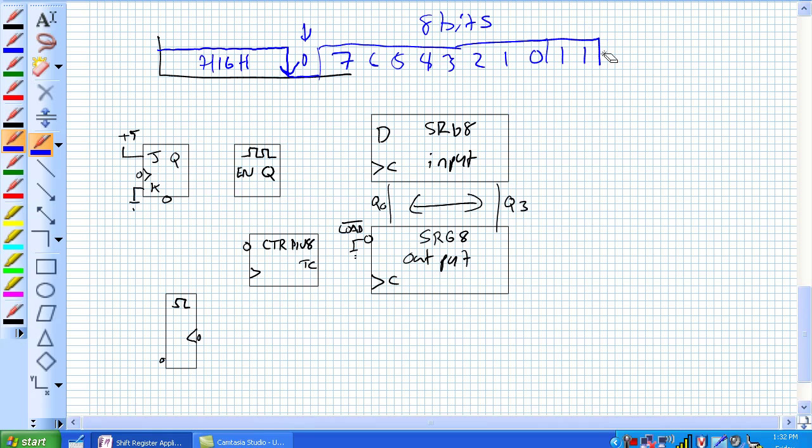And again, if you were going to send more data, you'd go back to 0. But if you aren't sending data, it would just be 1 waiting for that next transition. So these are the packages here that we're going to see. We're always going to see that high to low transition after a long period of 1s, a 0 start bit, our 8 bits we want, and our 2 stop bits. So how many bits is that? That's 11 bits. Which ones are we really concerned with?